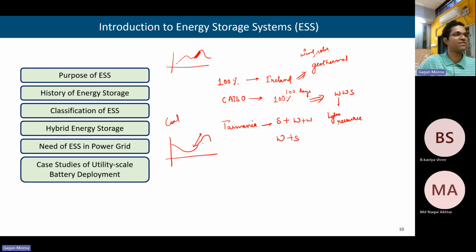And the thermal generators: let's say there are 1,000 generators. For meeting the base load, let's say 30% of generators are operating at their maximum because they are cheaper, and the cheaper generators would be scheduled first. So they are already operating at their maximum, Pmax.